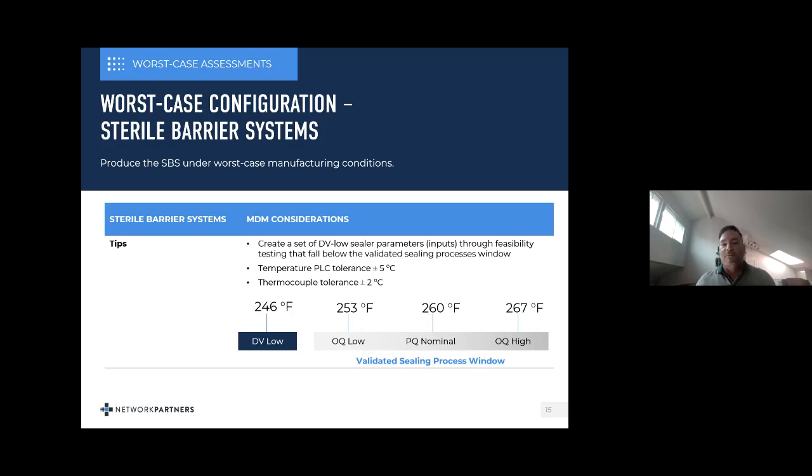So what I always stated in there, and if you look at 4332, it says if you don't really specify duration, it defaults to 72 hours. If you know what the equilibrium is in the chamber, you can reduce that. So I highly recommend that piece. But what I've done in the past is specify and say, okay, you're going to sit your samples out in ambient lab conditions for, let's say, 4 hours. Then I'm going to stick them in a chamber at negative 18 degrees because I knew equilibrium was reached under 8 hours, and just said for a minimum of 8 hours.